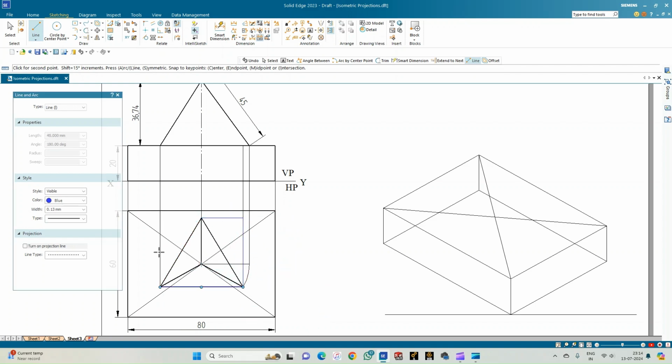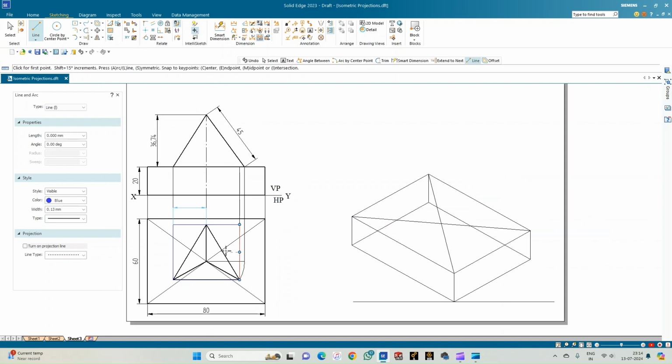the rectangle so that I get to draw this rectangle and then mark the points. So now what I can do is I can construct this rectangle on the surface of the rectangular prism and then mark these points, say 1, 2 and 3, and then complete the construction of the tetrahedron. And from this point of intersection, take the axis which is equal to 36.74 and then complete the projections. So now let us begin the procedure.